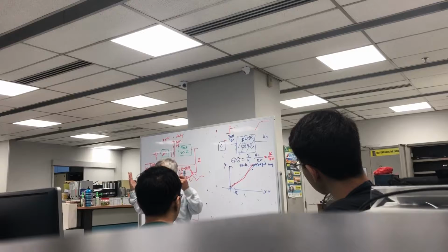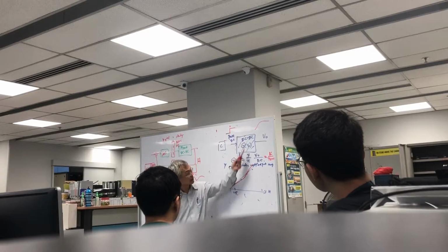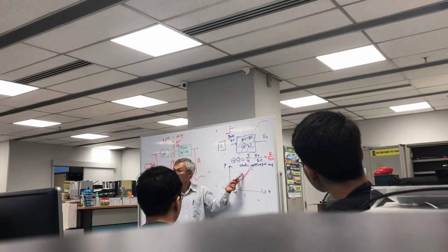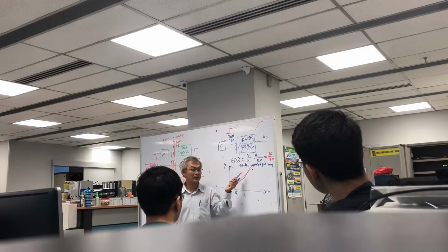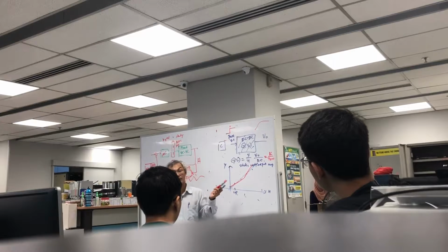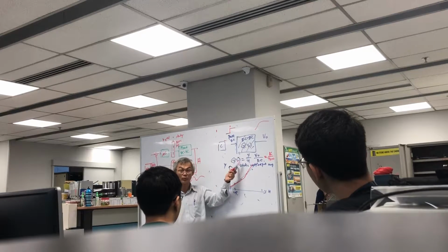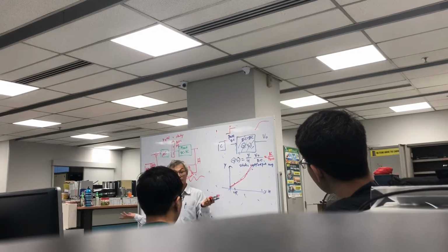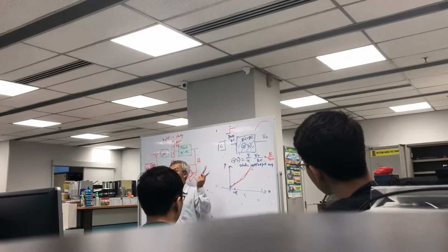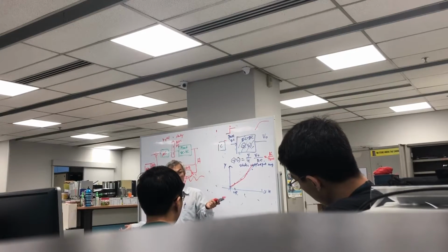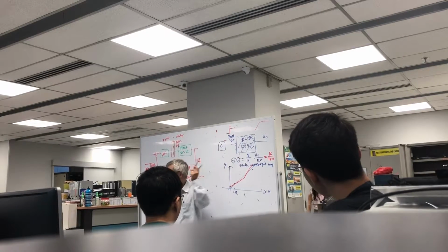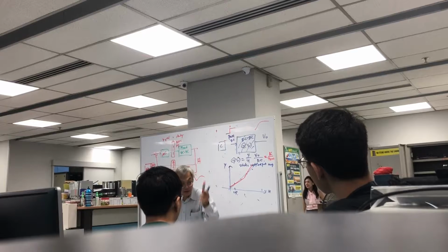So again, I'm talking in general. To do this kind of test, what are the assumptions? To do an open loop test, what is the most important assumption? The plant is open loop stable. If the plant is not open loop stable, you cannot do it. Alright? Before you carry out any test, you must make sure that it is safe to do. And by the fact that you use transfer function, you are implicitly assuming linearity.